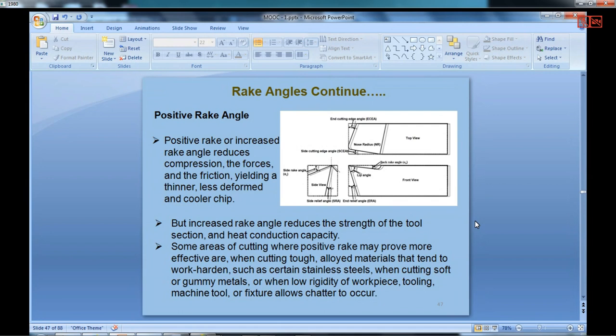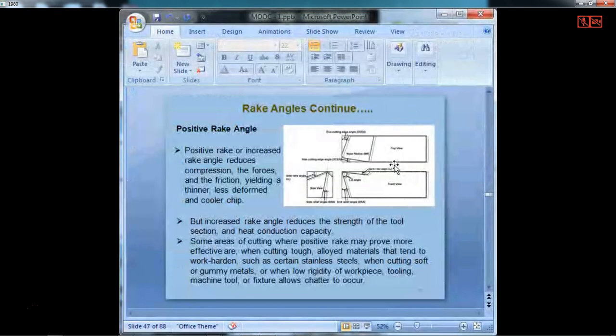Probably sometimes you would have looked at the machining processes, you see the workpiece becoming red hot. Nowadays we have cutting tools with a very high hot hardness, a term called hot hardness. That means even at higher temperatures, they retain their hardness. So even when it has become red hot, still the hardness is maintained and the machining process goes on. But how do you remove that heat?